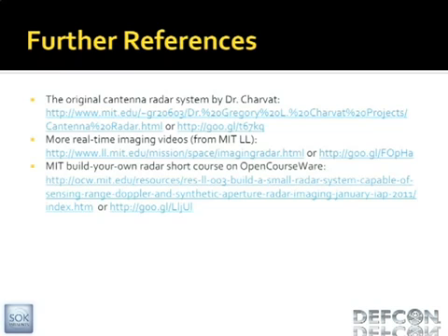He asked if I was looking at software-defined radio systems. I think there would be some benefit to that. Certainly the SAR coherent processing would benefit greatly from an FPGA system, because it can take a few seconds to process an image like that on the computer. But in this case, the main goal was simplicity and low cost. If you bring in one of those research boards, like the USRP, that's going to add a big chunk of change to your design. But there's definitely a lot of potential there. I would say that's absolutely worth exploring. Anyone else?